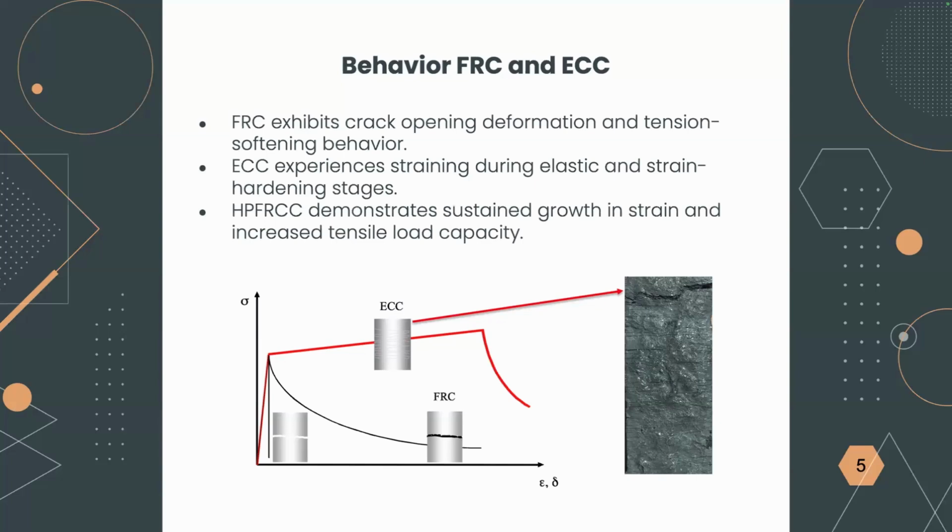So we start to move the bottom end, and then we measure the ability of the material to take tensile forces. So for example, for conventional concrete, we would have the load keeps on increasing until it reaches the failure point, and then we have a vertical line. This vertical line means the material is brittle. It doesn't have any ductility. So that's denoted by the vertical line.